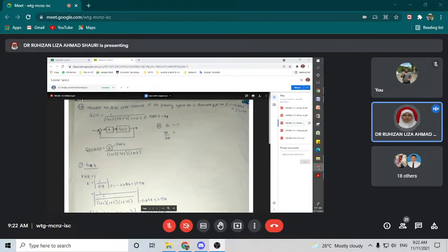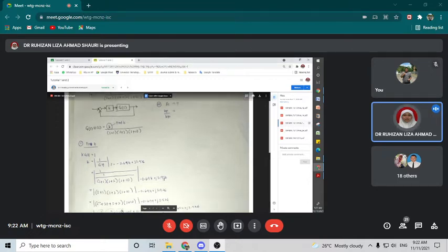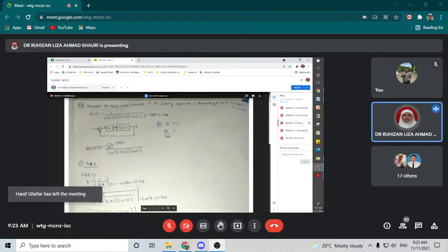Okay, let me continue. So the question is just asking you to calculate the static error constant, with the given dominant pole at that point: minus 0.694 plus j 3.926. That's the point given in the question. Please refer to tutorial 1D.